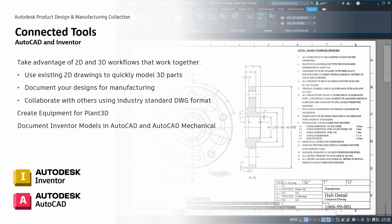That's sort of that interoperability too, right? So if I need to create a tank or a vessel or a pressure tank, I can create it inside of Inventor to a high level of fabrication detail, and then directly save it out to a format that Plant 3D accepts, and it actually accepts the pipe connections as well. It's called an ADSK export. And that's been in the software for some time.